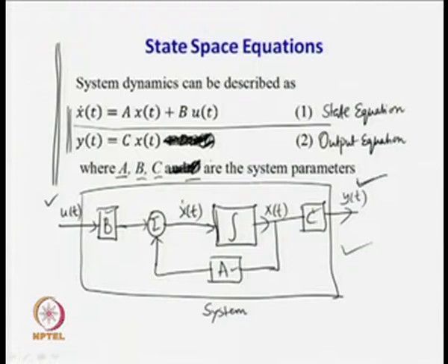Now, practically, what information do we get from this type of block diagram? Suppose I have got a first order system without any delay, then what do I get from there? Suppose I have got y s upon u s equal to K upon T 1 s plus 1. I have not included the delay term in this for ease of analysis.